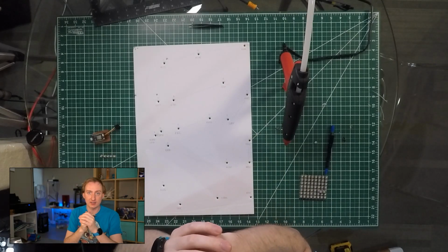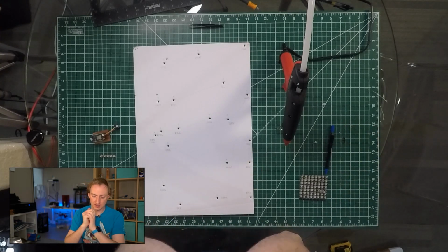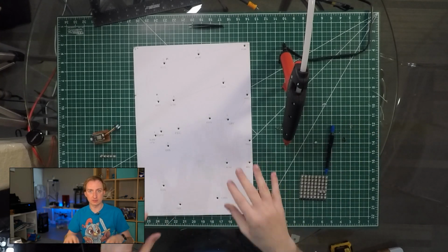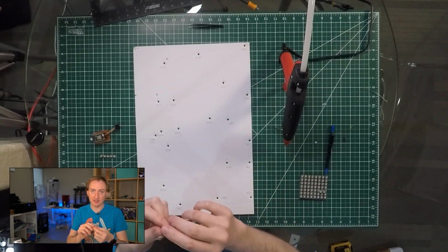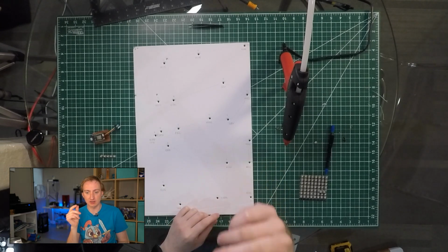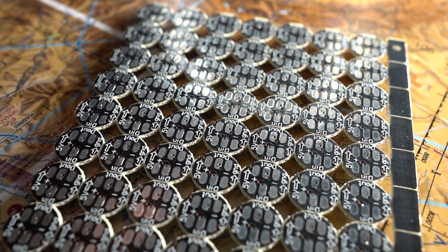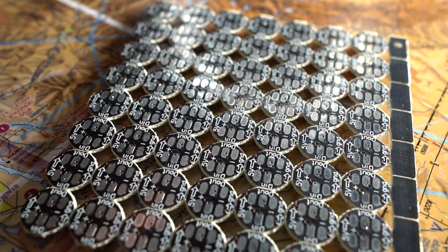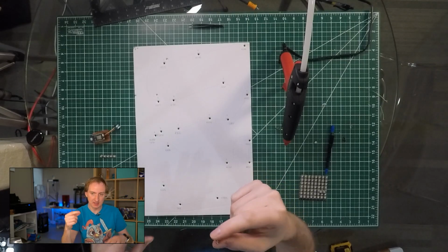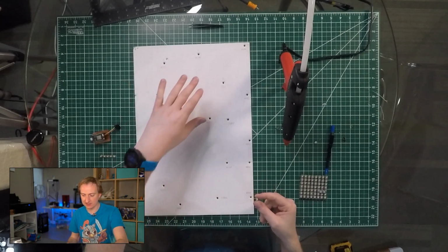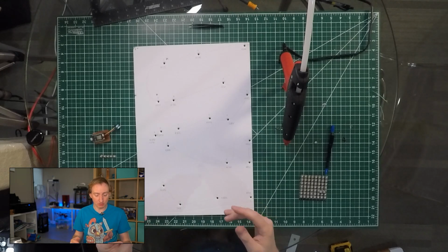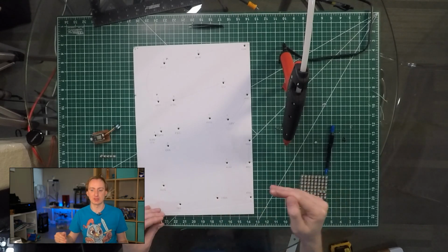One quick thing before I get to using the hot glue gun is to note some of the small things I'm doing to make sure I glue these correctly. You can't really see it on any of the cameras here, I'll try and get a close up for you. They have 6 pads on the bottom, 3 of them in and 3 of them out. So I have to lay them out on the back of this thing so that I can later solder the wires on them correctly.